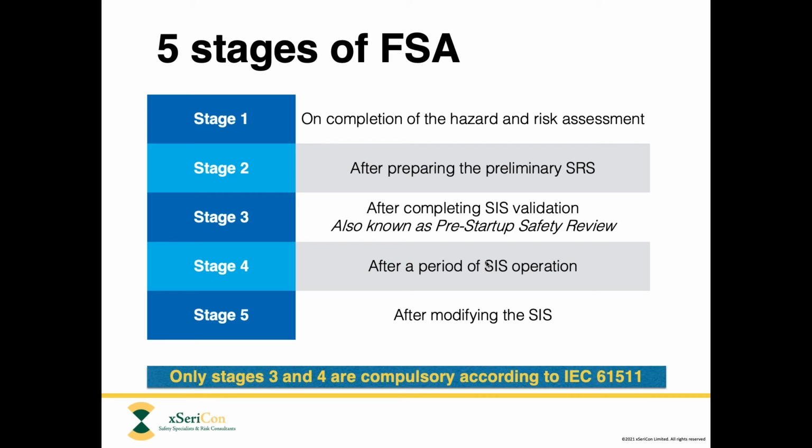So normally you only need to do validation one time during the life cycle, although if you, after startup, do some modifications to the safety instrumented system, you usually need to revalidate, but only for those specific modifications that were made. Validation is also known as pre-startup safety review, or PSSR. It's essentially the same activity.